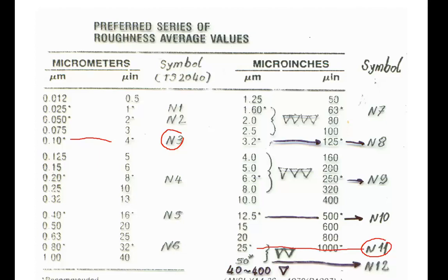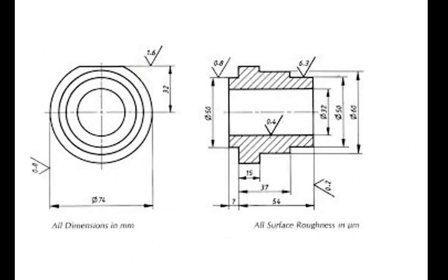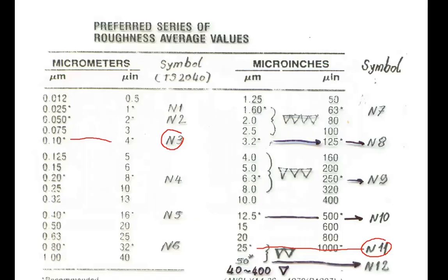This is also the table to convert the triangles to roughness values in the old standard, which was valid at the time. There was no profilometer. We used the finger test only. For instance, on a technical drawing like this, the quality symbol is 2 triangles. Two triangles means roughness height may be 25 or 50 micrometer.